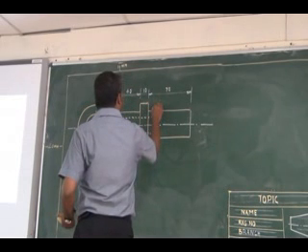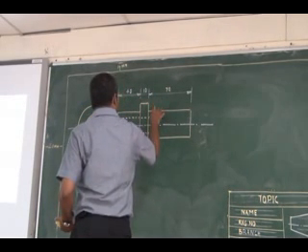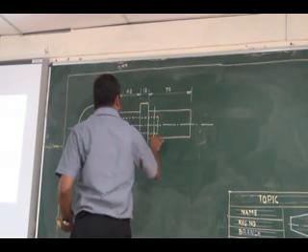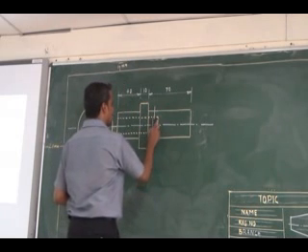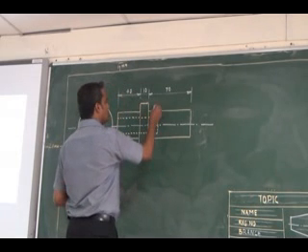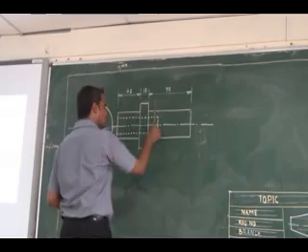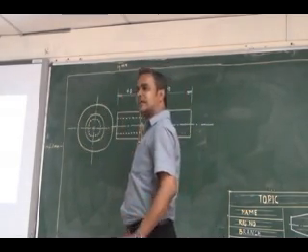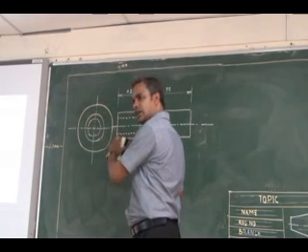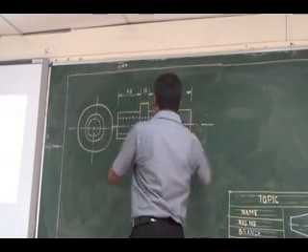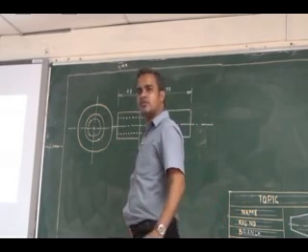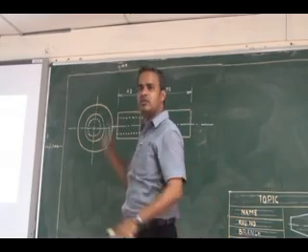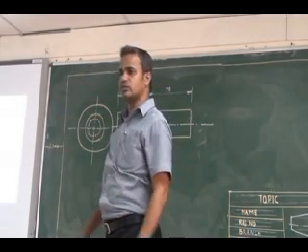I am representing a cutting plane. This is a portion. I am going to introduce an imaginary cutting plane which cuts the solid. I am removing one half of the portion, and I am going to look at how the solid looks in a view.